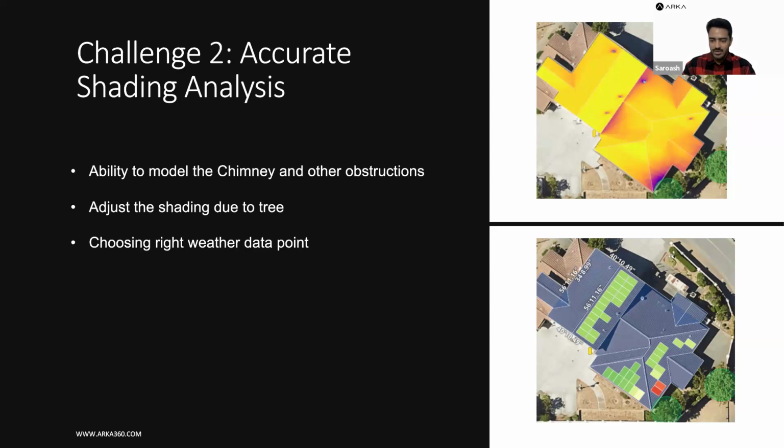In the second one, I've tried to place the panel on the east side of the first roof and on the south side and east side of the second roof. Since there is no shadow on the first roof, all panels are green. The green indicates that the TSRF, or the sunlight you are getting, is maximum there. The ones shown in the black, red or yellow spectrum are getting shaded, and you're going to end up losing some percentage of the generation and compromising your overall system size.